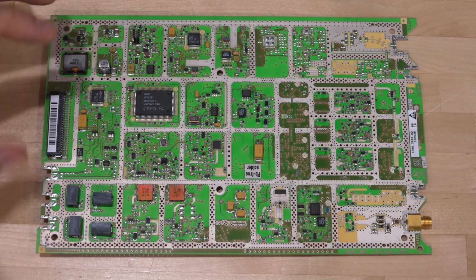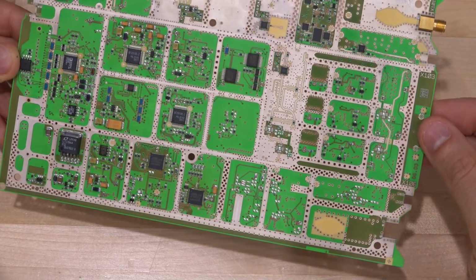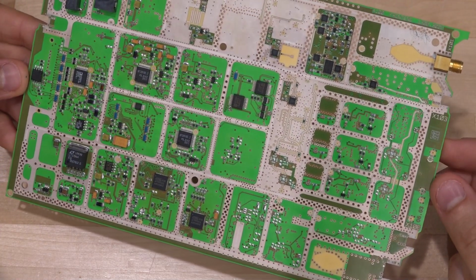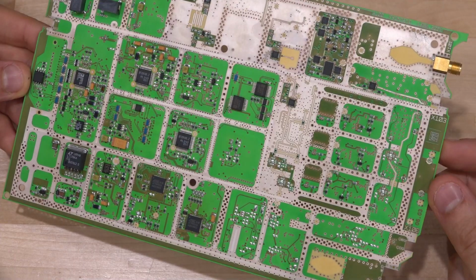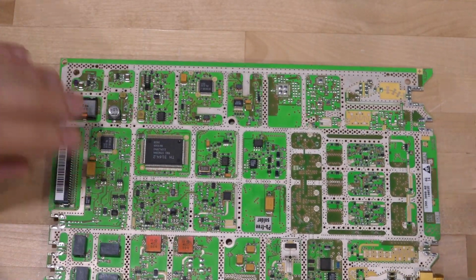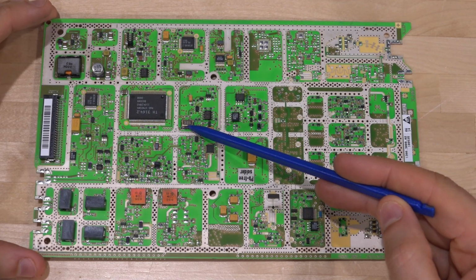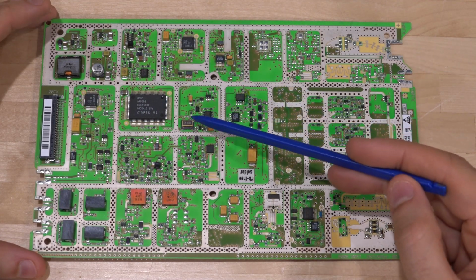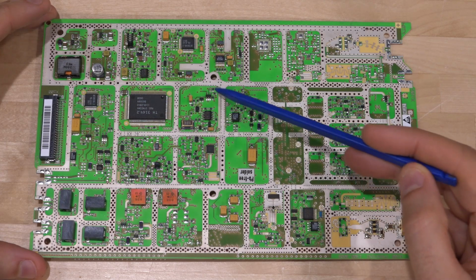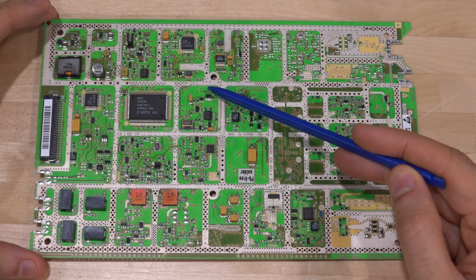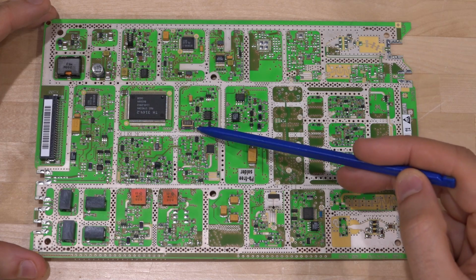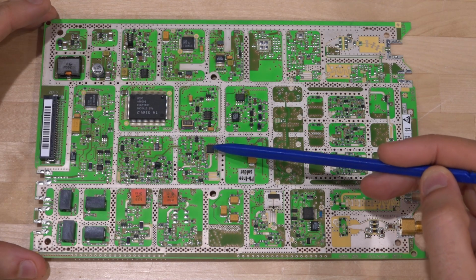So let's find the core of the PLL. Let's go on the other side a little bit. Let me take a brief look here. All right, so what I think is going on is that we have what appears to be a TCXO, that's 10 megahertz. That's going over here in this area. This TCXO is connected most likely to over here, and this is probably our VCO.